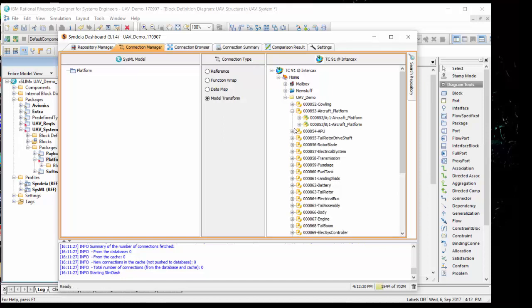Here we have a choice. We can use the Teamcenter item, or we can use a specific Teamcenter item revision, like B.1. If we use the Teamcenter item, our SysML blocks will always be connected to the latest version of the Teamcenter item. If we use an item revision, we are connected to a specific configuration of the item, at least until we choose to update the SysML model at a later time. In this case, we will use a specific item revision.